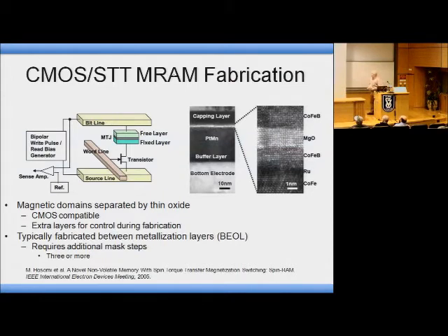So there are classical ways, and this again shows that image. In a memory structure, we've got a sense amp, we've got bit lines, and you can literally build this MTJ above this access transistor. You can look at the word line and the transistor, and you can access, and that access device sets you up into the MTJ, and you actually fix that impedance, and that defines it. So when you read it or write it, you're looking at the current, which is going to be determined by the resistance of that MTJ, and that's important. So that difference in current is due to the difference in resistance, and therefore it's important to have a wide resistance differential. Again, I repeat some of the same points.